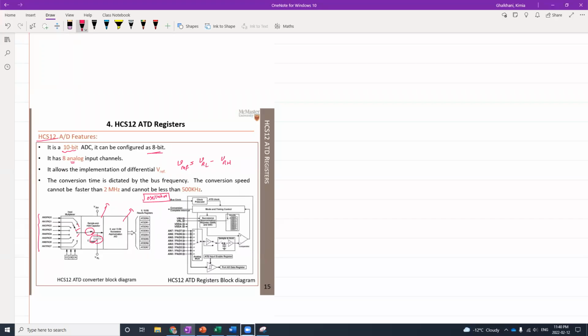If I have 16 megahertz in here, right, which is the natural frequency, then the main bus is half, which is let's say 8 megahertz. Then I need the scalar, which is this guy. Let me just make it bigger.